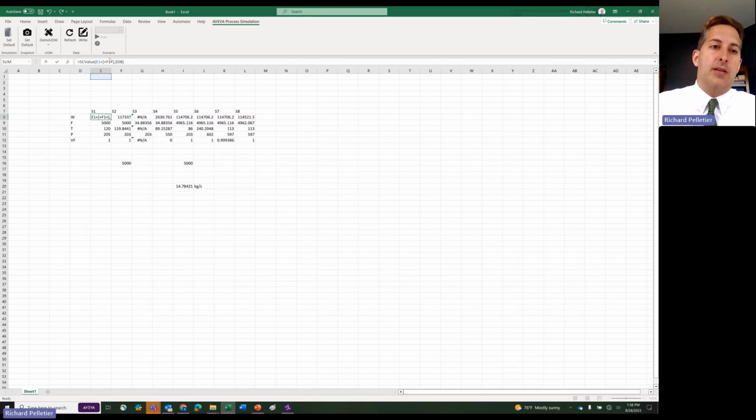So what I would recommend, if you are going to try to use any sort of referencing where you're trying to pull properties that are made up of multiple parts, right? Whether that's compositions, column tray results, element results for multi-element models like number of tubes in a plug flow reactor and stuff like that. You have to utilize that capability in order to properly set up the referencing.